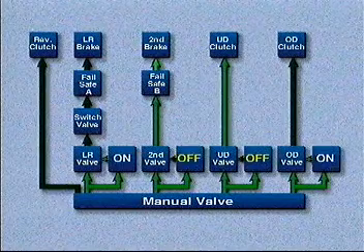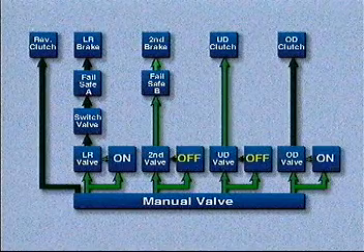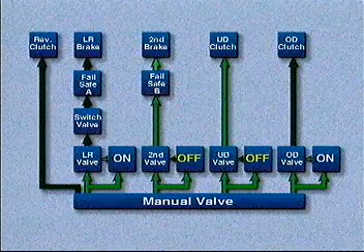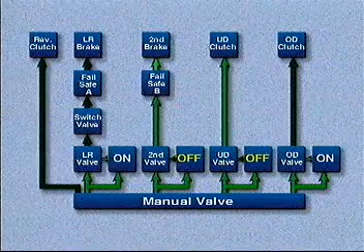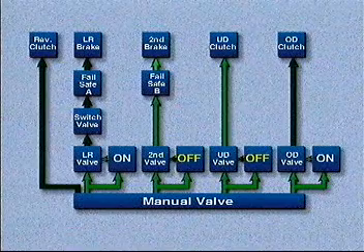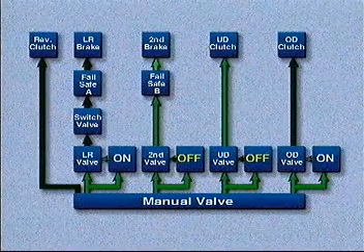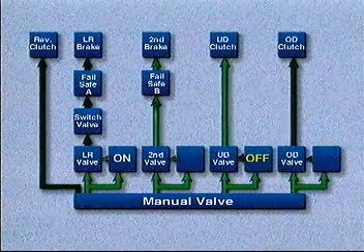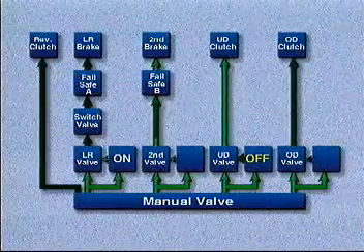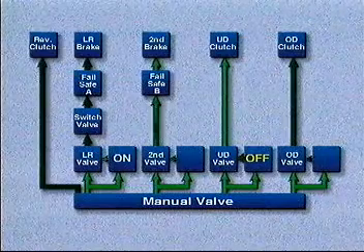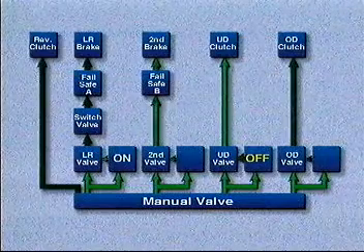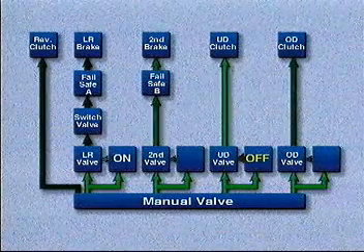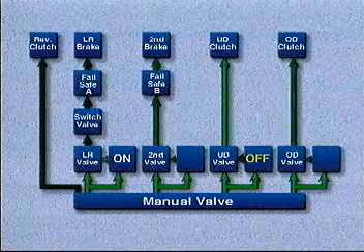In second gear, the overdrive clutch is not used, and so its solenoid valve is on. This blocks line pressure from acting on the overdrive pressure control valve. The pressure control valve prevents line pressure from being applied to the overdrive clutch. During a shift from second to third, the overdrive clutch is applied as the second brake is released. The timing of release and application of friction elements is critical to prevent internal transaxle lockup. Application is gradual for a smooth shift.